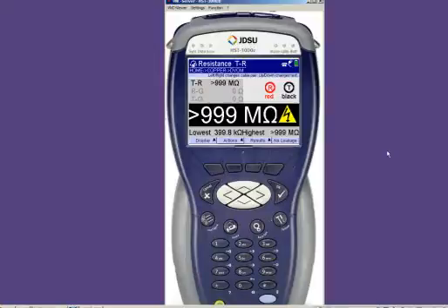A note on this 120 volts: it is a super high impedance supply. What I mean by that is if you wanted to pick up an ordinary meter and just measure the voltage coming out of the ohm meter on the HST, you would not see anything near 120. You would have to have a real high impedance lab type meter to see the actual voltage come out.